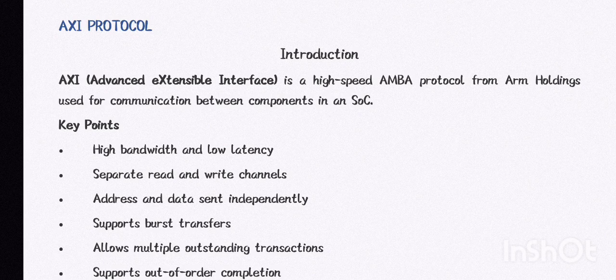It is suitable for memory controllers with high initial access latency, and provides flexibility in the implementation of interconnect architectures. It is backward compatible with existing AHB and APB interfaces.